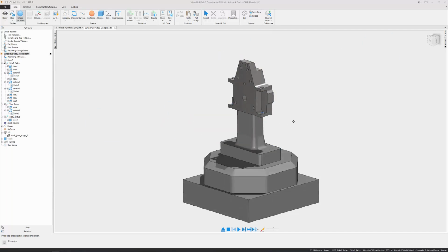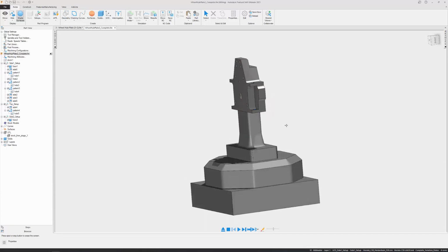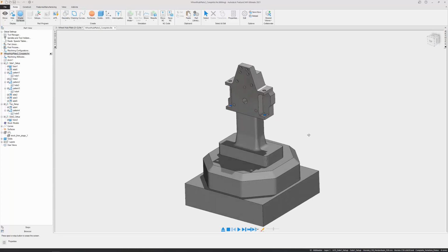So awesome. With that, we completely machined this component using 2 different setups and 2 different machines, which is pretty cool. We started on our Haas VF4, just machining this bottom face so that we had something to hang on to for our 5th axis setup. And not only that, we were able to save our simulation results as an STL, ensuring that further operations didn't end up creating any tool path that would result in air cutting for this secondary operation on our 5-axis Hermle C30 machine. It looks like we're safe, and we have a completely machined component.